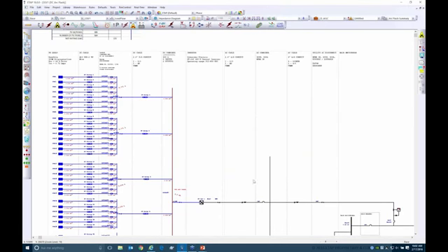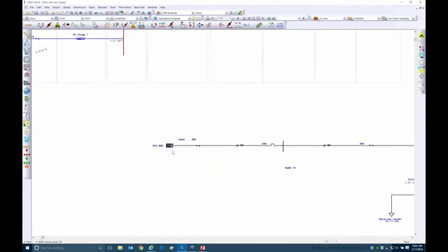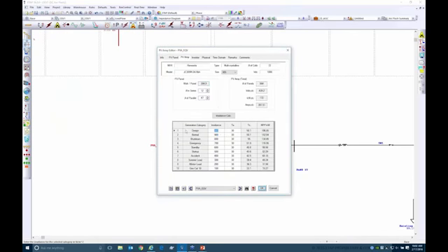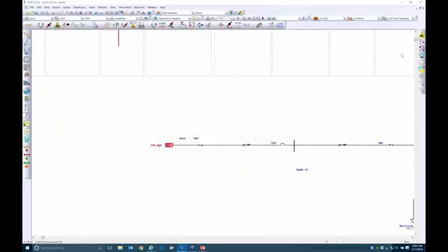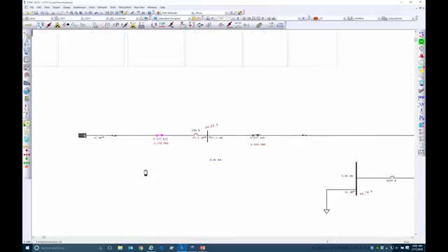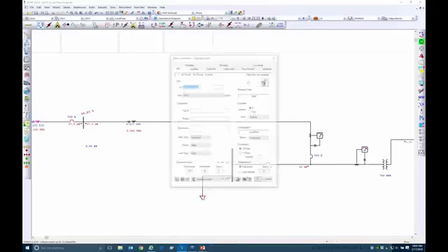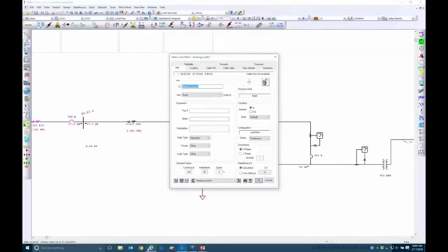So if I take 613 watts per square meter and apply it to my model, and that ambient temperature probably corresponds to about 22 degrees Celsius, and if I run my power flow calculation, I should have been seeing about 98 kilowatts from these panels. I should also change my load correspondingly.